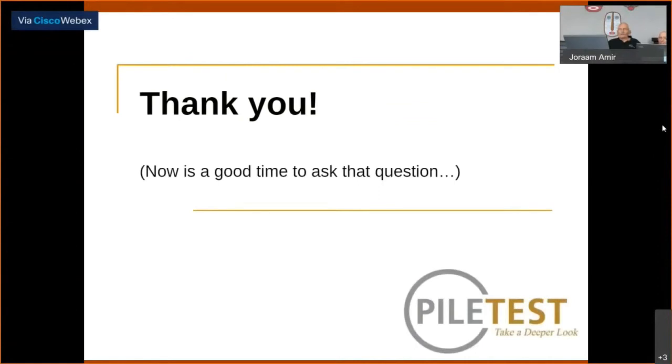And option number 3 is to reject the pile altogether. I don't like this option because today's piles are in many cases large diameter, deep piles, very expensive ones. And to reject the pile is just your last recourse. Don't do it unless there is no other choice.